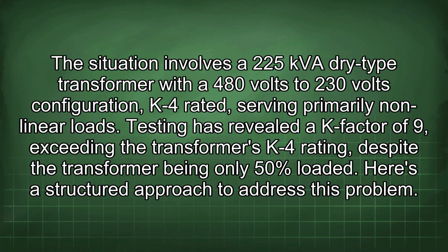This situation involves a 225 kVA dry-type transformer with a 480 volts to 230 volts configuration, K-4 rated, serving primarily nonlinear loads. Testing has revealed a K-factor of 9, exceeding the transformer's K-4 rating, despite the transformer being only 50% loaded. Here's a structured approach to address this problem.